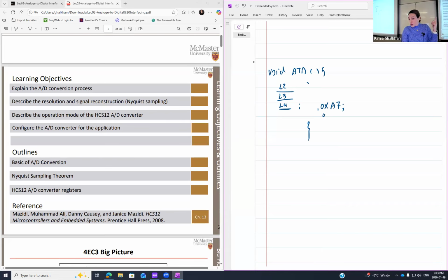And then for register 4, most of you for 8-bit resolution, your finding was 0x87 or 85. You can remember? That was your hex calculation or hex equivalent for resolution.